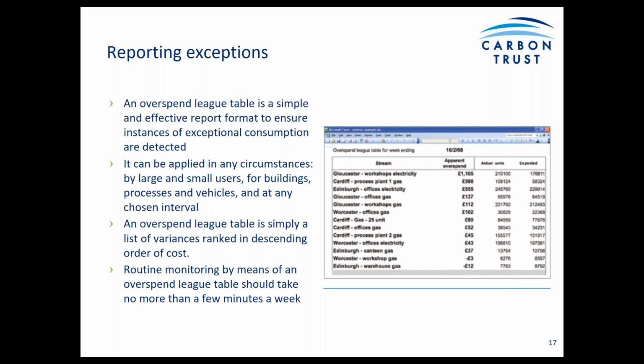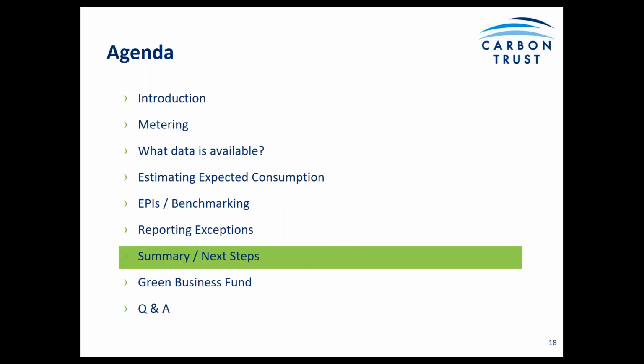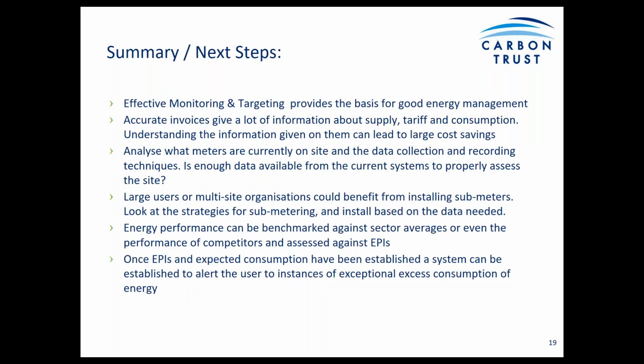So routine monitoring of energy consumption by means of something like an overspend league table, as I say, is relatively simple and should potentially only take a few minutes a week once a system like this has been implemented. So in summary, effective monitoring and targeting provides the basis for good energy management.